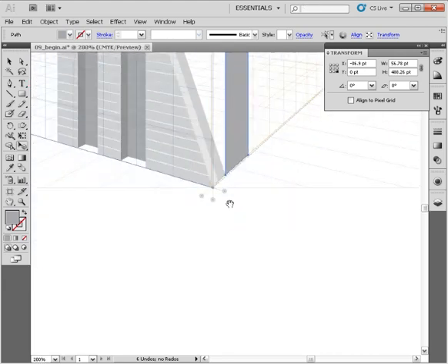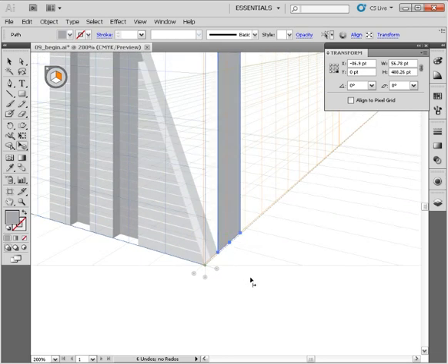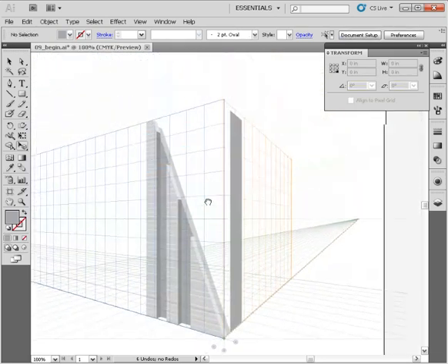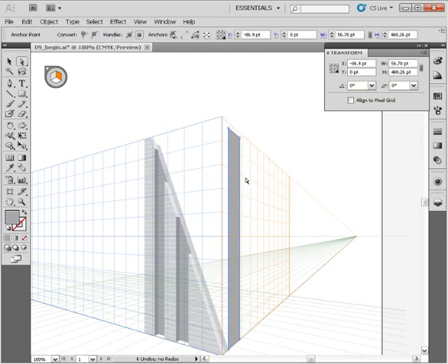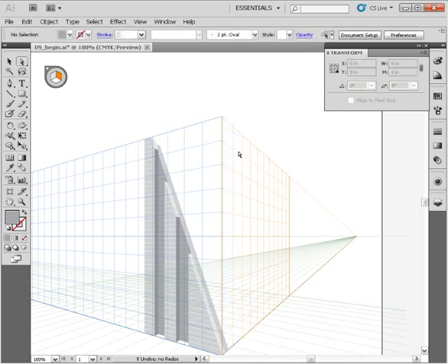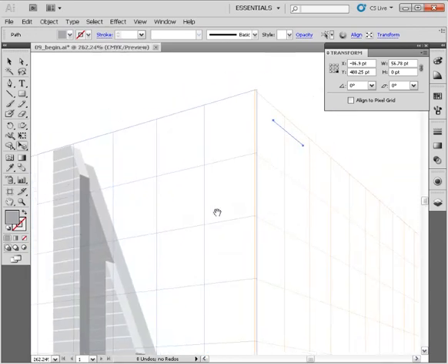So we've got at least the bottom part of this object in the right position here, and now all that's left to do is use the same trick that we've used in previous lessons to move this top path back and then recomplete this shape. So I'll use my direct selection tool, and we'll delete these side paths here. Then let's grab this object with our perspective selection tool, just this top path, hold down the keyboard shortcut 5, and move that back perpendicular.